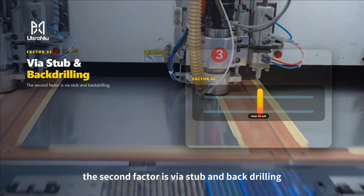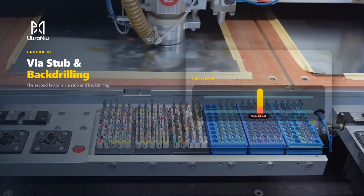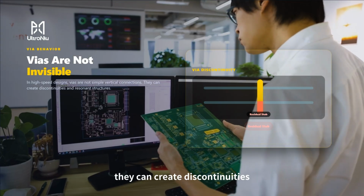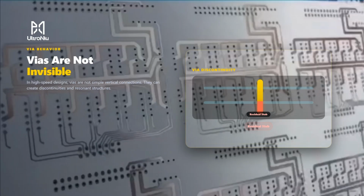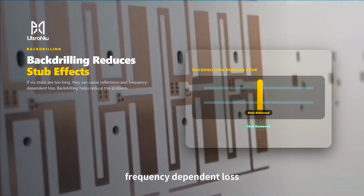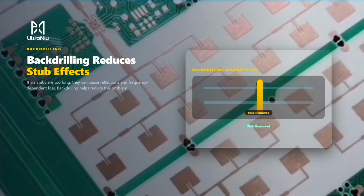The second factor is via stub and backdrilling. In high-speed designs, vias are not simple vertical connections. They can create discontinuities and resonant structures. If via stubs are too long, they can cause reflections and frequency-dependent loss. Backdrilling helps reduce this problem.